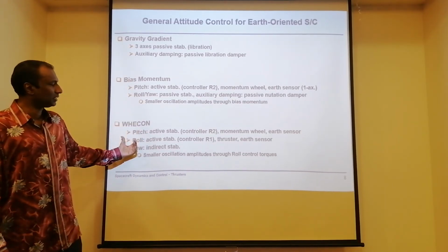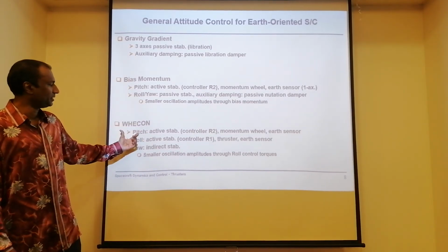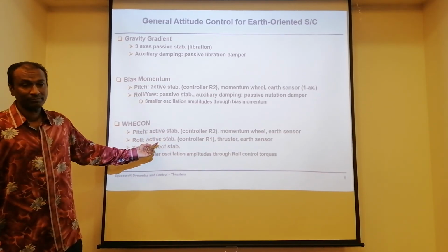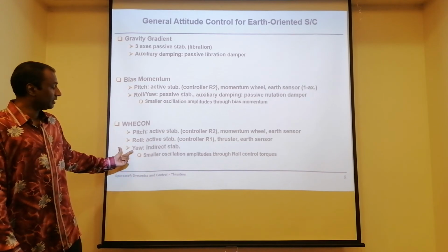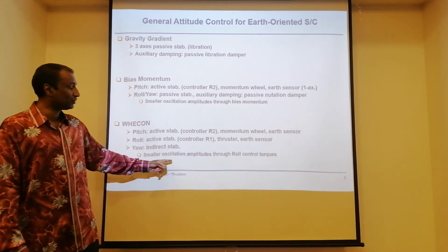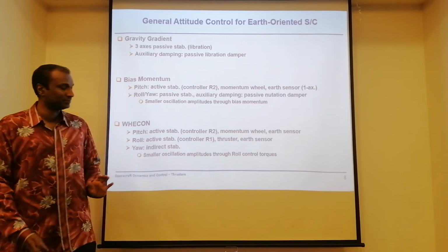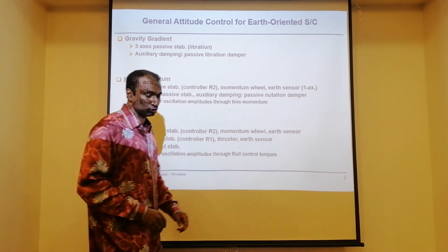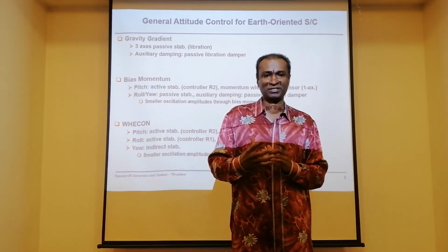Pitch. So the actual solution that we have here, pitch is active because I have my wheel. Roll is active. I have my thrusters. Yaw is indirect. Okay, yaw is indirect. You can still find a smaller oscillation, but through the roll control torques, practically it dampens.